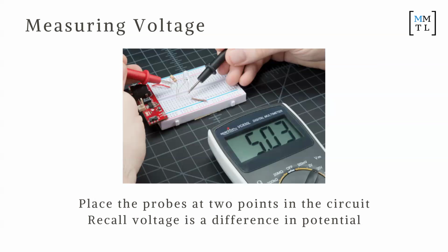Well, the button's not pressed, right? So therefore it should be 0. I'm expecting 0, so hence it's 0. If you press the button, it goes up to -4.3. Do you remember our TTL logic? If it's above 2.2, then it considers it a 5, right? In this case, it's 4.3, so I can change the polarity of this, and then I'm going to expect to see positive 4.3. So what it really operates at is 4.4. Does that make sense?